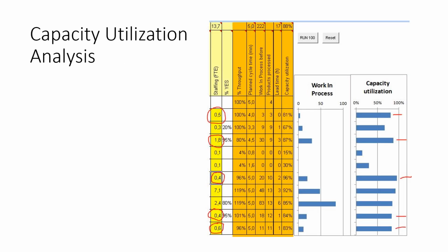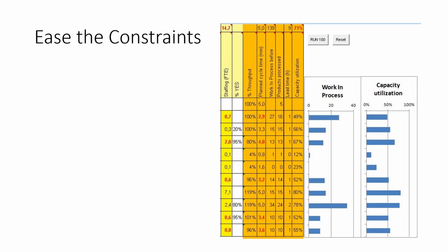Repair and functional test are the two operations which add value and consume most resources in the value stream, so we would expect to have high capacity utilization in both. When there is an increase in arrivals, we would expect a queue to form, causing an increase in the overall lead time. We don't want other steps, which require low staffing, to become a bottleneck for the line, so with a small increase in the staffing of those steps, which have high capacity utilization, we can make sure they never become the bottleneck.